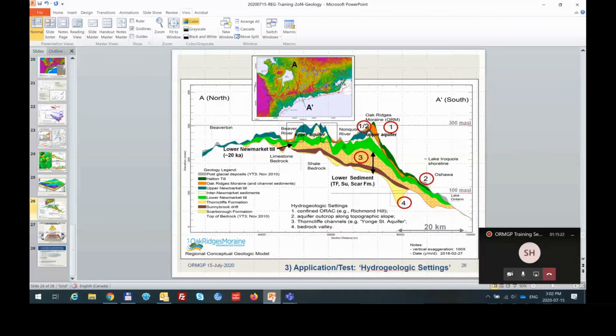And when you incorporate something that's got the wrong units into your geologic interpretation, they'll often show up as bullseyes or huge mountains. So there's a lot of that. Plus, maybe you have 20 wells in an area, and the driller logs the sediments a certain way, and then another driller may come in and drill a borehole, and they log sediments differently. So you have to bring that into consideration.